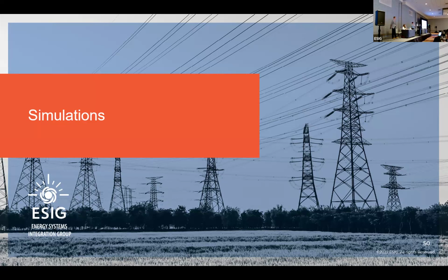But the thing is, our switching is ideal in the programs. So generally, switching is going to produce impacts at really high frequencies. And in our opinion, it is probably not going to have an impact on things that happen in the time frame of a transient stability study. But that's essentially my thought on that. Great question, though.